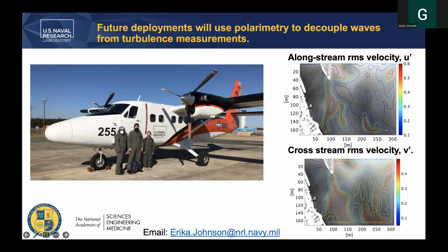Can I ask a question? Sure. Okay, well, actually, a couple of questions. So one is from what you just said. You try to reconstruct the turbulent velocity based on the surface behavior, but the theory used for the surface behavior for the waves is based on a flow without turbulence. So I wonder, how do you make sure that the surface responds within the time scale of turbulence, which can be much shorter than the one of the actual surface fluctuations?